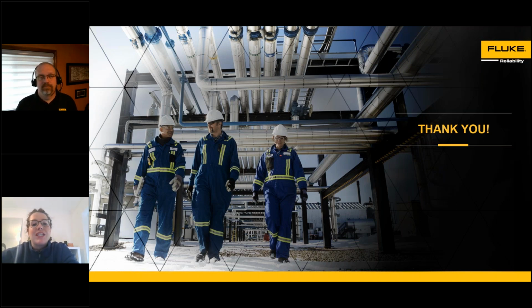Do you recommend vibration analysis for reciprocating compressors? So it has value, but due to the nature of reciprocating compressors, there's a lot of noise going on. And so what you'll want to do, when you're doing vibration analysis on reciprocating compressors, is pay close attention to your overalls. If you're seeing an increase in your overall energies, that is indicative of something changing. Once you know that something is changing, that'll allow you to do a little bit of a deeper dive, and hopefully you'll be able to find the specific thing that is beginning to fail.